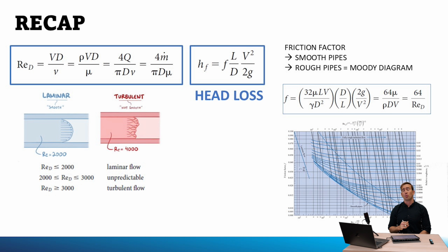What we discussed today was conduit flow. Essentially, everything we talked about was entrance length, figuring out how long it takes the fluid to get into its final flow type, turbulent or laminar. Then we talked a little more carefully about how you calculate the friction factor in the pipe and how that depends on Reynolds number and this thing called the roughness coefficient.